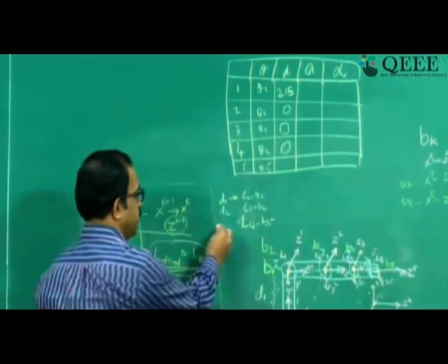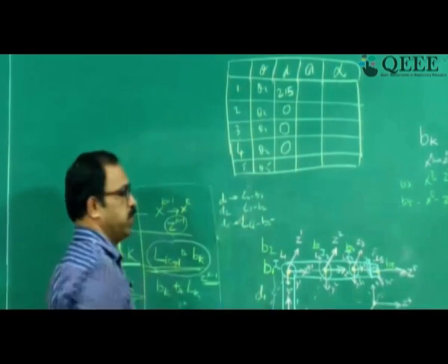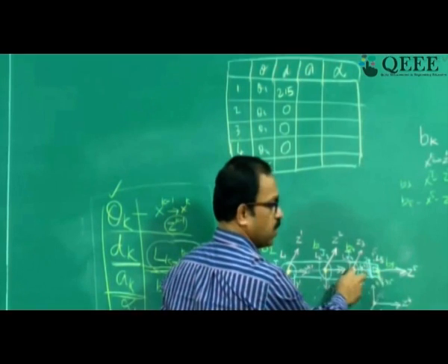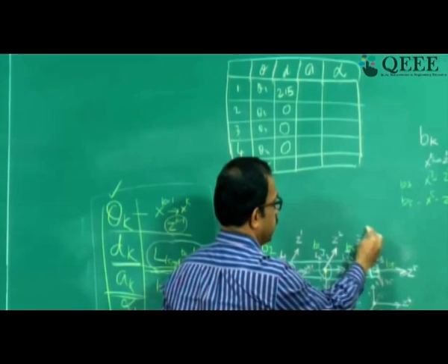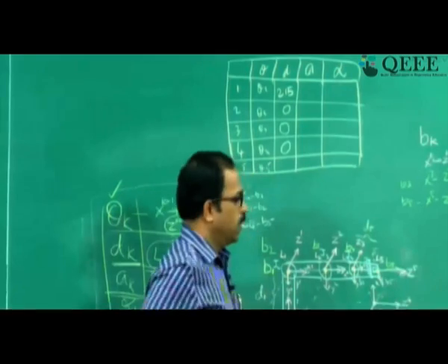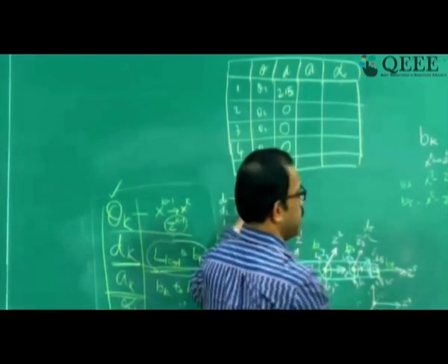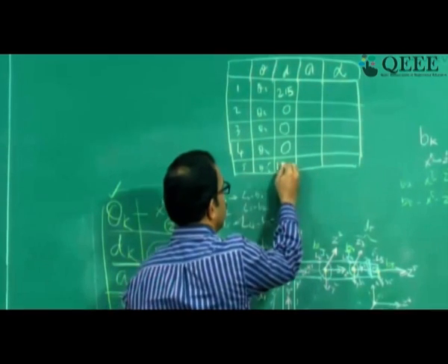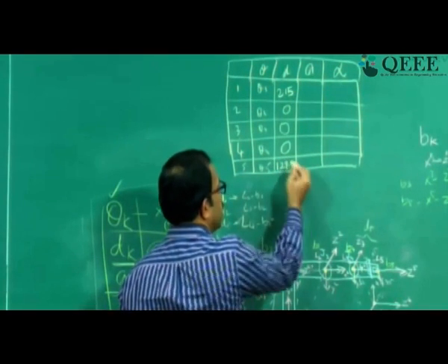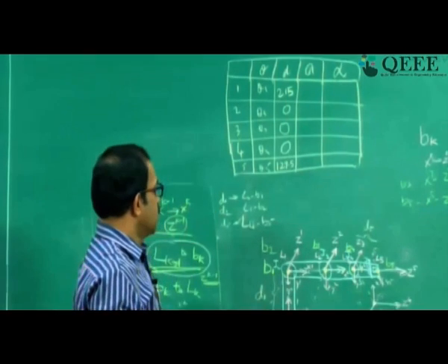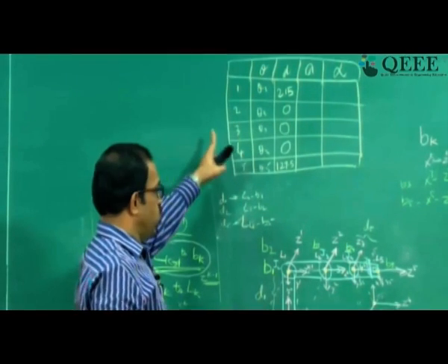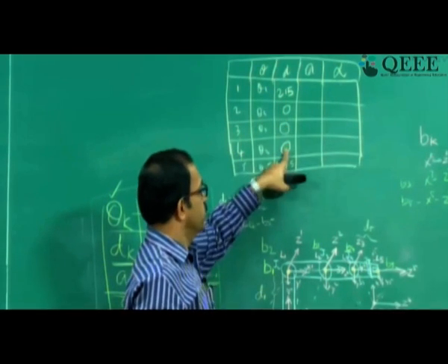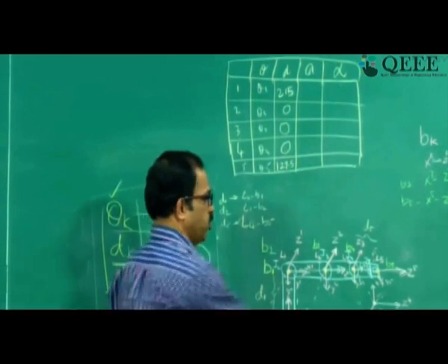L4 is here at the same point, B5 is here, so this distance is D5, which from the diagram is 129.5. So we got all the joint distance parameters: 215 for D1, D2, D3, D4 are 0, and D5 is 129.5.